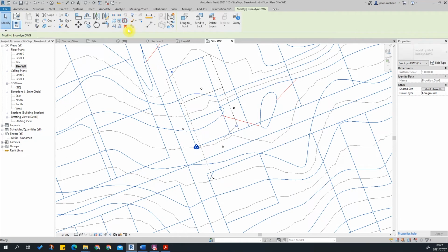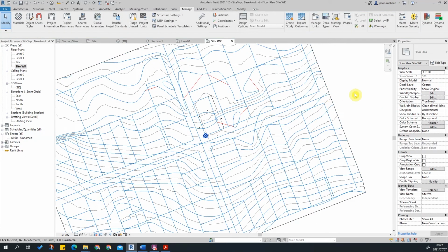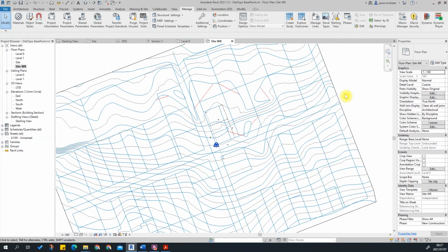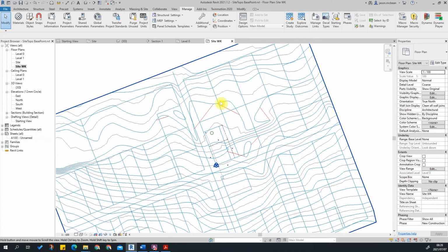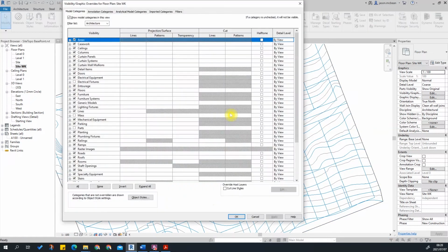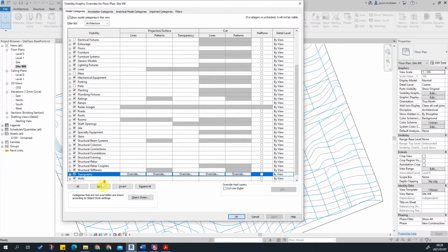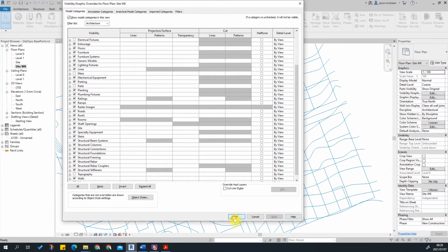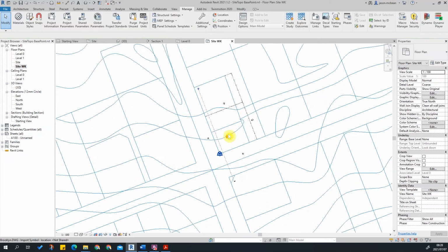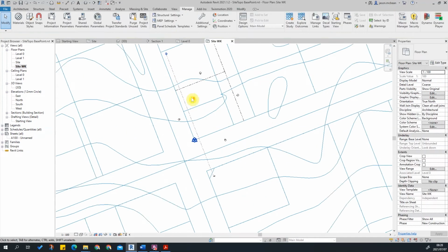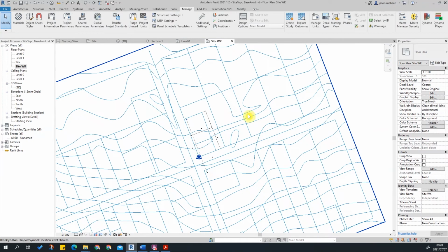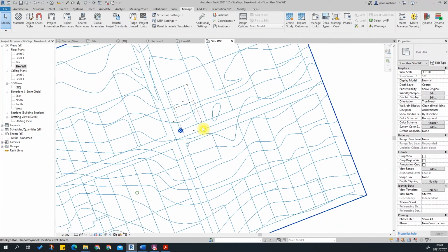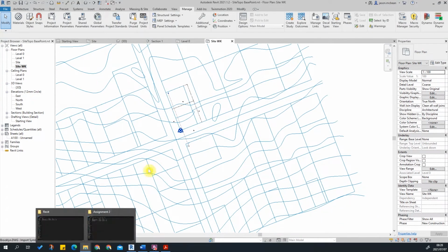If it's not already pinned, you're going to pin it so that you can't accidentally delete it or something like that. That usually happens. And what I will do in this case is I'll go to VG and switch off my topo surface for the time being as well. All right, so we've just got a pure AutoCAD file, we've got some basic site information, and we've got the road center lines. Now we just need some aerial photographs to help us refine the site a bit further.